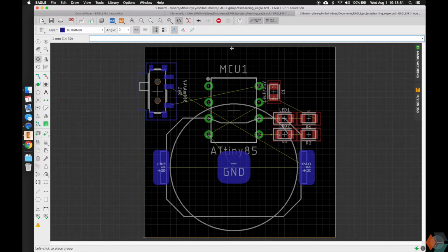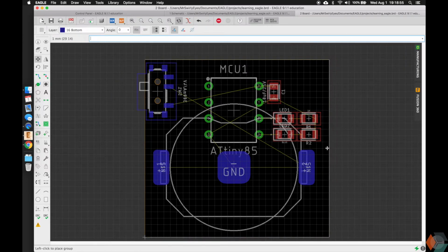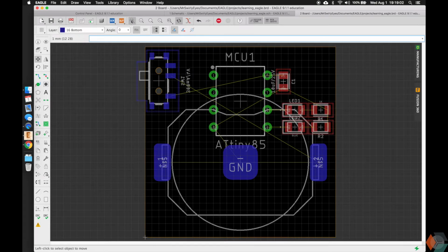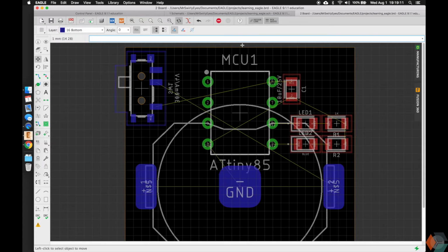I can make the board a little bit smaller, so I will. We'll move this in a little bit. There we go. So it's still within the design constraint. It would have yelled at us if we made it too close. Cool. So one thing to keep in mind is the larger the board, the more money you're going to pay for it. So it's good to make your designs as small as possible. However, again, since this is an art, maybe some of your designs have things wide or big or some fancy design that makes the board a little bit larger and thus more costly, and that may be what you want to do. All right, so everything is placed the way I want it.